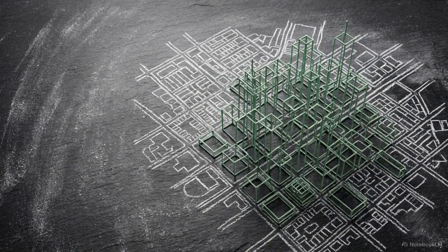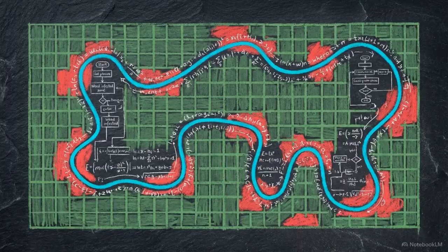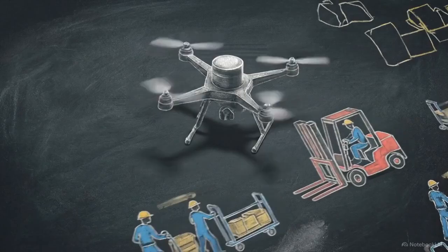In dense structured environments, this evolutionary logic is highly effective. Drones running GA and DE capture 16% more data during urban LiDAR missions than those flying standard uniform grids. LiDAR is a remote sensing method that uses pulsed lasers to measure distances and generate precise 3D maps. In precision agriculture, applying GA to analyze images and map specific weed-infested zones yields an 88% efficiency increase over uniform crop spraying. The limitation is time.